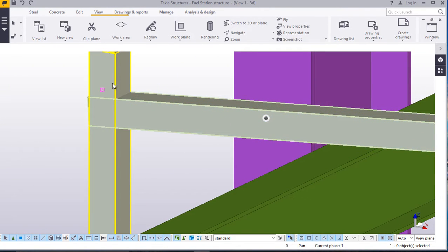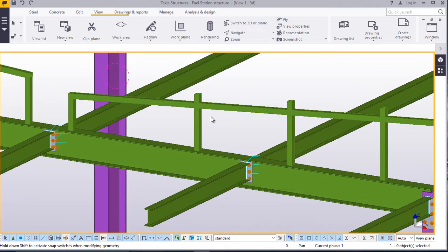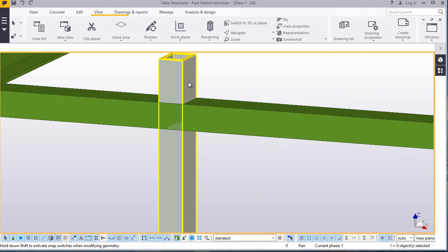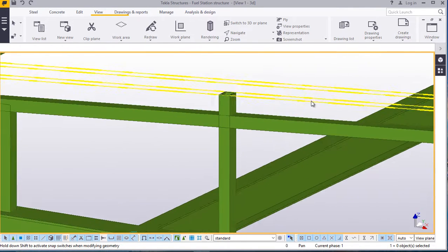Now what we are going to do is to shorten these struts as I did in part 1. Just click and press your left button on the mouse and drag it down, place it there. We'll come to trim it perfectly later on. Click that, drag it down like that.